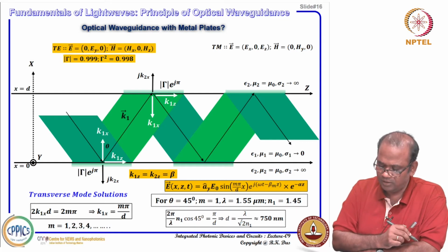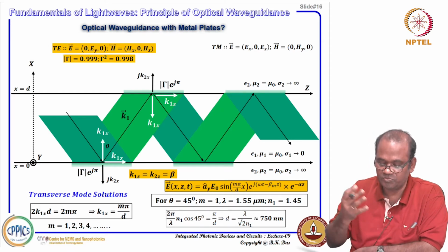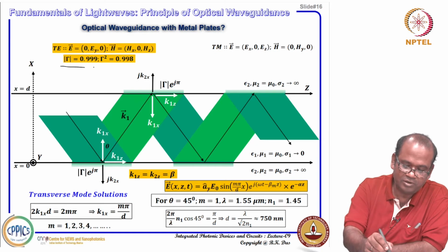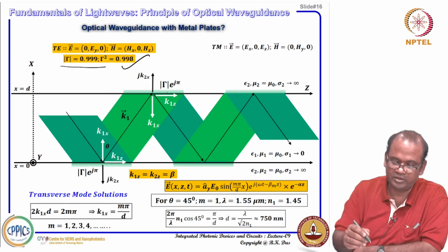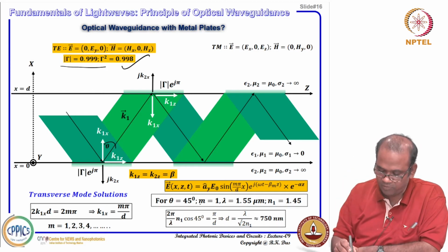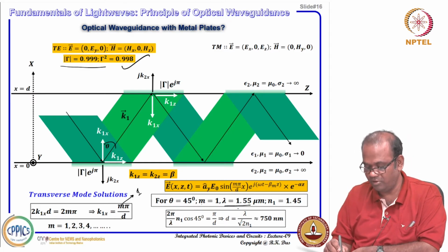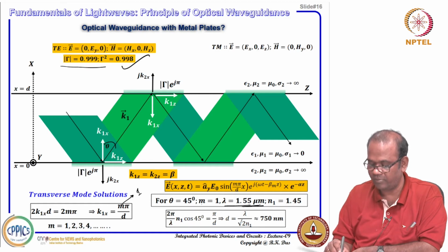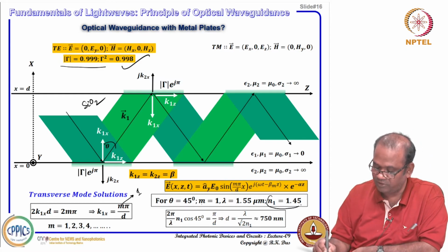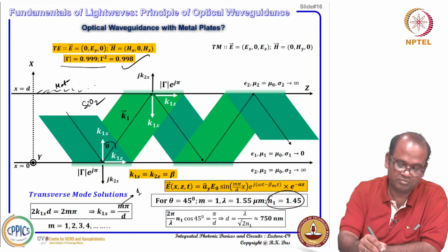For microwave, normally, if this wave is considered as an optical wave where lambda is very small, we can consider, for a typical example, gamma equal to this one and gamma square will be this one, that is reflectivity. A little bit of loss is there in the optical domain, for example. And if we consider theta equal to say 45 degree, and for a mode m equal to 1, I am considering here 1, and the optical wavelength is the third optical communication window, 1550 nanometer, 1.55 micrometer. And if you consider this is SiO2, silicon dioxide, then at that particular wavelength the refractive index is around 1.45.